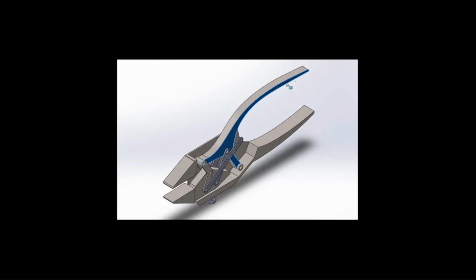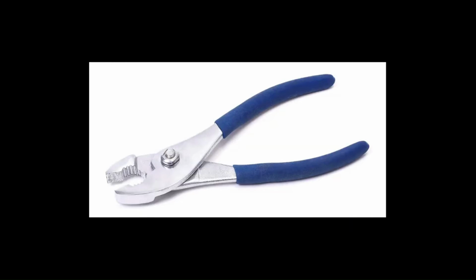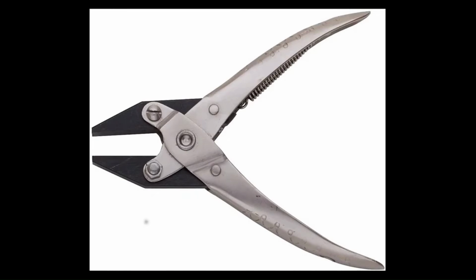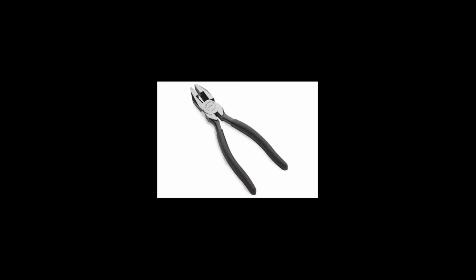Parallel jaw pliers are prime examples which use the Chebyshev 4-bar mechanism. Parallel jaw pliers are a kind of pliers which excel at crimping and grasping near the tips, since they apply uniform pressure across the whole face as the jaw faces stay parallel. These pliers may be used in a pinch to hold or turn small fasteners without deforming its face. There are two pins which slide in the slots.